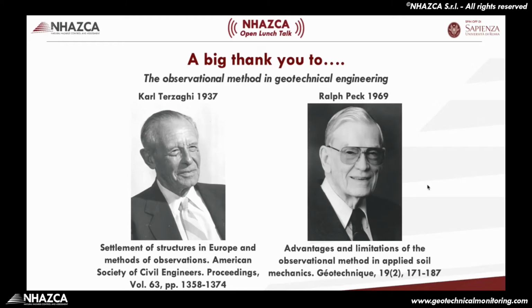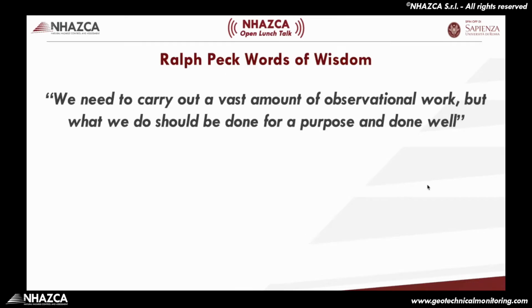They were quite conscious that geotechnical engineering and geology are full of uncertainties. So the uncertainty is something we have to deal with. It's a little bit less true for the structural field, but in geotechnique and in geology, the uncertainty is something that we must deal with. And so, starting from this assumption, looking at what is going on during construction is a relevant part. And so that's the concept and the reason for the observational method.